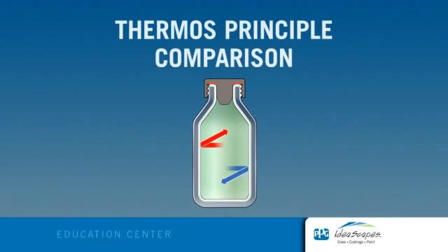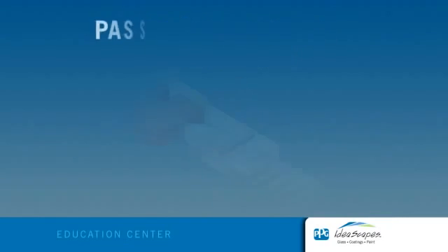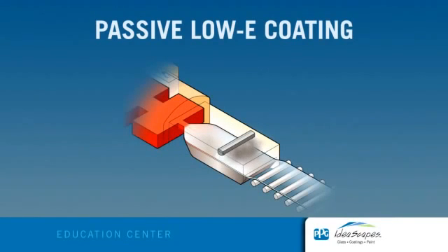The temperature is maintained because of the reflection that occurs, as well as the insulating benefits that the airspace provides between the inner and outer shells, similar to an insulating glass unit. Since low-E glass is comprised of extremely thin layers of silver or other low-E materials, the same theory applies. The silver low-E coating reflects the interior temperatures back inside, keeping the room warm or cool. There are actually two different types of low-E coatings: passive low-E and solar control low-E.